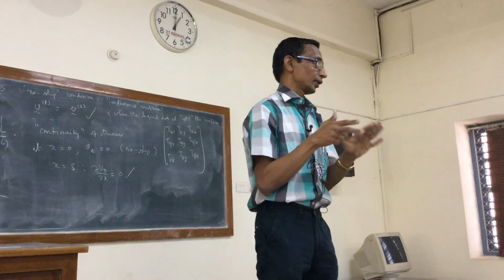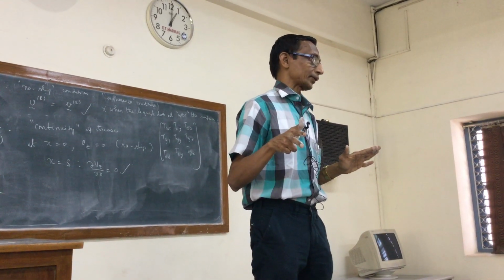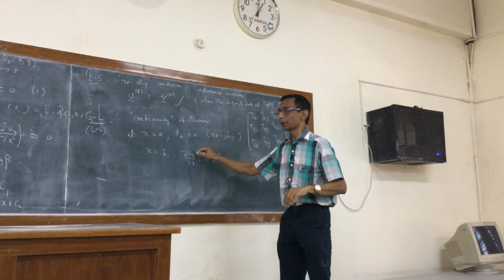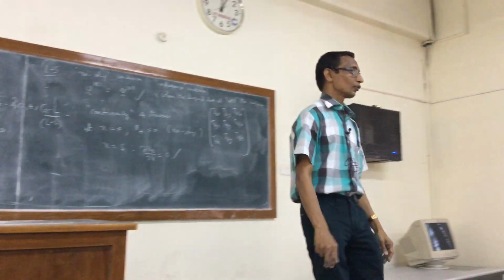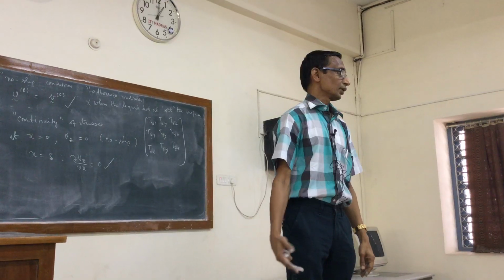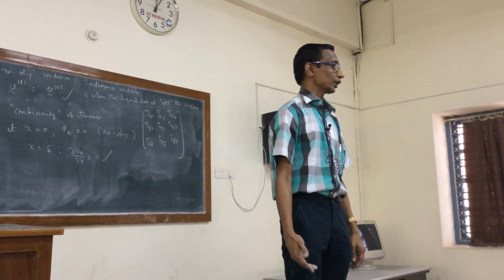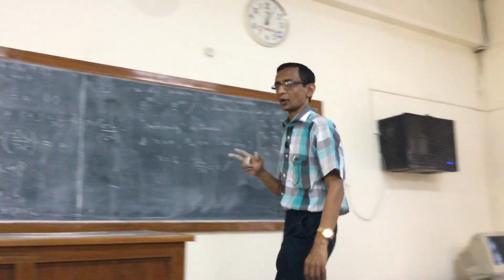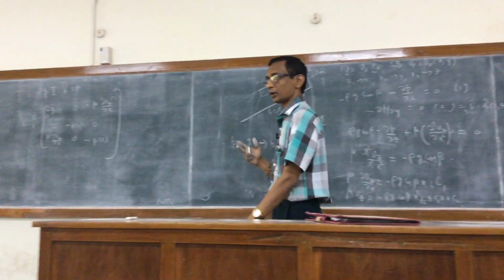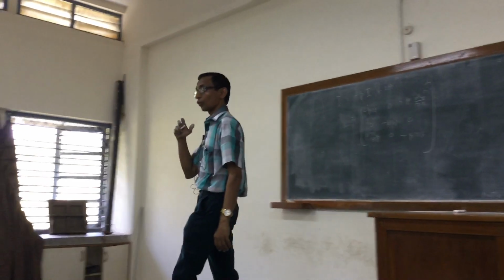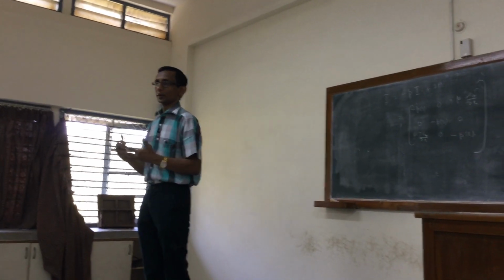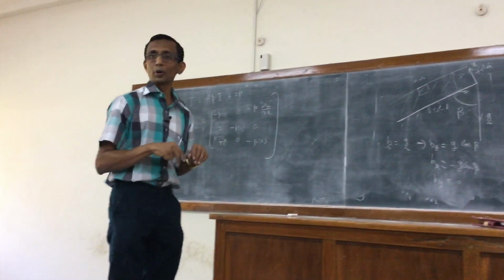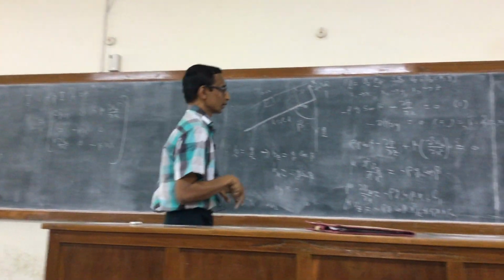We clearly know that the mu of the liquid cannot be neglected. So we conclude that dVz by dx must be 0. That condition arises out of the continuity of stresses along the liquid-gas interface. You have to be aware that boundary conditions are always a problem, and there is no one uniform rule. You have to look at the particular fluids that are in contact with particular surfaces and then arrive at them. These are typical boundary conditions that come into play in simple situations.